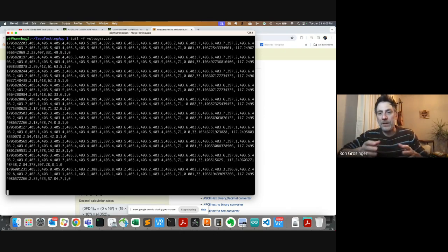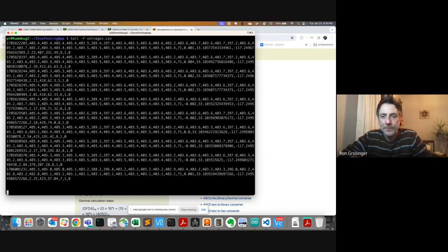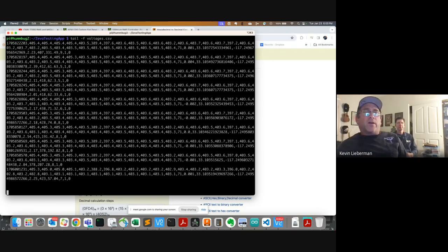Now, is that because on one CAN you don't just have the BMS, you also have your GPS? Is that why? Right. I've got GPS and I've also got a current sensor. But I could be gathering data from multiple sensors all over the car to give me data back that could be useful later in analyzing my problems, or maybe tuning the car for better range or anything.